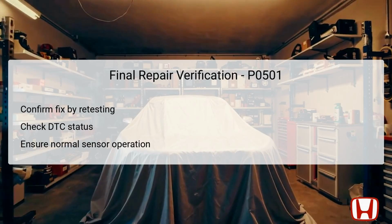Monitoring the DTC status is equally important. If the code does not reappear during this phase, it is a positive indication that the problem has been addressed. Ensuring that the CVT speed sensor operates normally after the repair indicates that the vehicle is back to optimal performance. This verification stage is essential for customer satisfaction and maintains the integrity of the vehicle's performance standards.